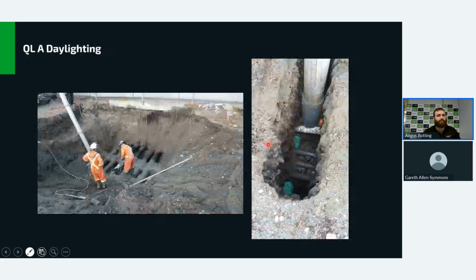And then after all that, if there's still areas that need higher assurances, or we want to make sure that the information provided is 100%, especially if it's on the crossing, then we're going to advance it to the standard, more traditional quality level A. We're going to hydrovac, we're going to find the bottom of the pipe, the top of the pipe, with the idea of the investigation bringing it up to quality level B first, deciding the route, then planning around that, so you can minimize the amount of daylighting and hydrovacing required, especially when it comes to parallel lines along your trench.